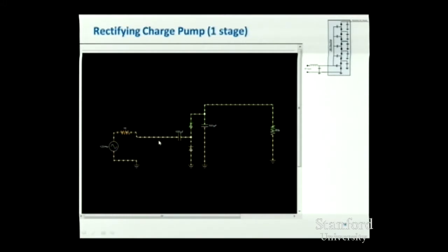So it's an AC or RF signal. And then if you look at the dots on the diodes, say the bottom diode, you can see that the dots are only going up. That's of course what the diode does. It only allows current to pass in one direction. If you look at it, you can see it's behaving sort of like a check valve, where again the current only flows one direction. So driving it with an AC signal in this configuration causes a DC output up here. If you look at the dots up here, they're only going one direction because of the rectifying action of the diodes.